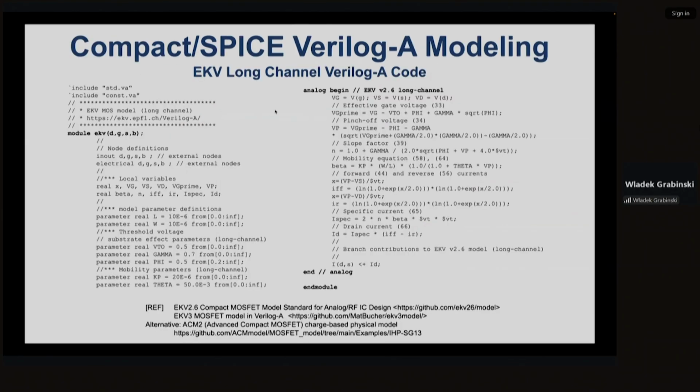Now we are coming to quite important part of OpenPDK, compact SPICE models. They are critical to maintain the high quality of OpenPDK, transistor level SPICE libraries, and all digital reference libraries. To introduce new SPICE compact model, we are recommending Verilog-A as a modeling language.